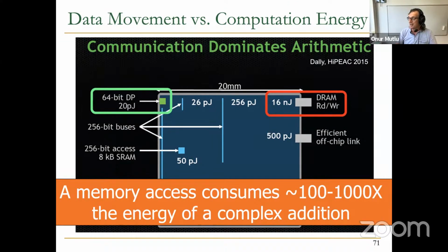So for example, when we talk about flash memory, you will see that read disturbance is a huge effect. In fact, we were doing a lot of research on flash memory and finding a lot of read disturbance problems in flash memory. That's what partially inspired us to look at essentially RowHammer also. So clearly, this effect exists in all memory technologies. In hard disks also, actually, read disturbance and write disturbance exist in other memory technologies as well. It also exists in SRAM.